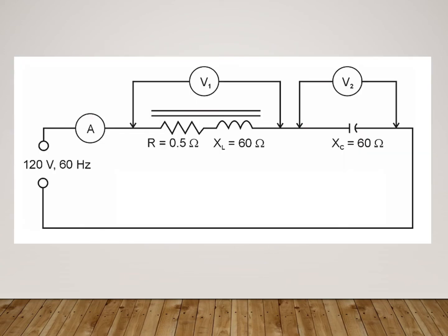So you might be thinking, well, Stan, if canceling out the X gives me a better power factor, why don't I just line them up so my inductive component and my capacitive component are the same? Therefore, I don't have anything to do. I'll have a power factor of 1, which is what we want. Well, that's all great. However, that is what's called a resonant circuit, and they do exist. However, in a series resonant circuit, it does create a bit of a complication.